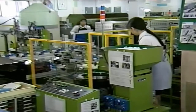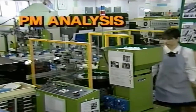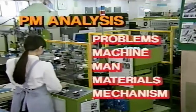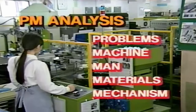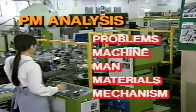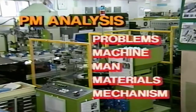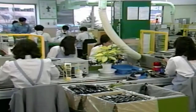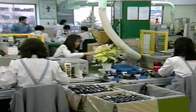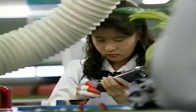The method of analysing the phenomena of short stoppages by theoretical explanation of what is different from the standard situation is called PM analysis. It leads to the drawing up of improvement plans. It's done by carefully considering the four factors of machine, man, materials and mechanism. If we think of the way things should be and rethink the factors based on the basic concept, we can then produce countermeasures to all minor defects. In the example we've just seen, the operation was automatic, so they didn't have to focus on the man element, but concentrated on the other three M's, materials, machine and mechanism in that order.